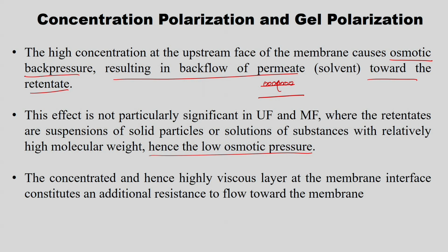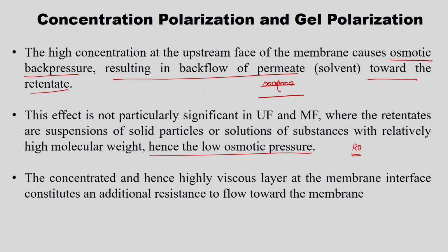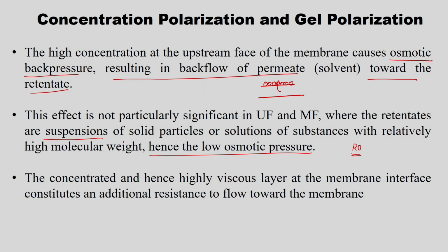Actually, concentration polarization is very dangerous in RO, because the retentate is mostly salt, and salts have high osmotic pressure. To overcome that osmotic pressure, when the backflow happens, it becomes an issue. But here this effect is not particularly significant, because the retentate in micro or ultrafiltration is a suspension of